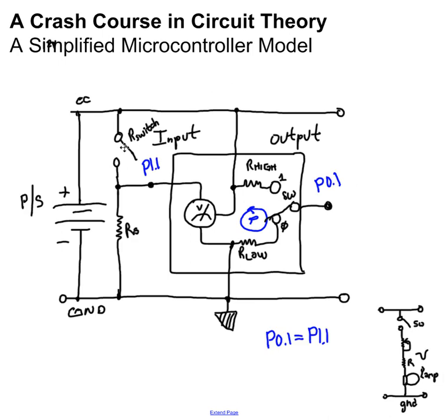If we look at this circuit, this is very similar to the series circuit that we had before, but this time we have removed the load and replaced it with a basic resistor. But it still will function in the same way as a digital output, whereas the voltage at this point will be 0 if the switch is open, whereas if I close the switch, the voltage will be connected to the power supply.